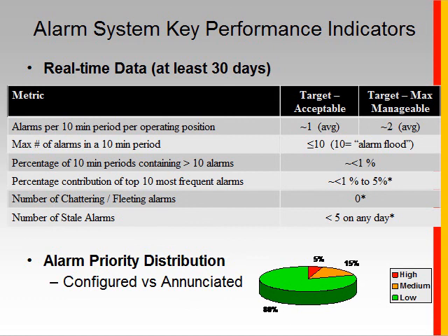Another thing we're going to measure is the distribution of alarm priorities. Back in the rationalization stage, one of the things that's suggested in the design process is to make sure that you have no more than 3 to 4 different priorities defined. Again, that has to do with the level of human comprehension to different types of information.